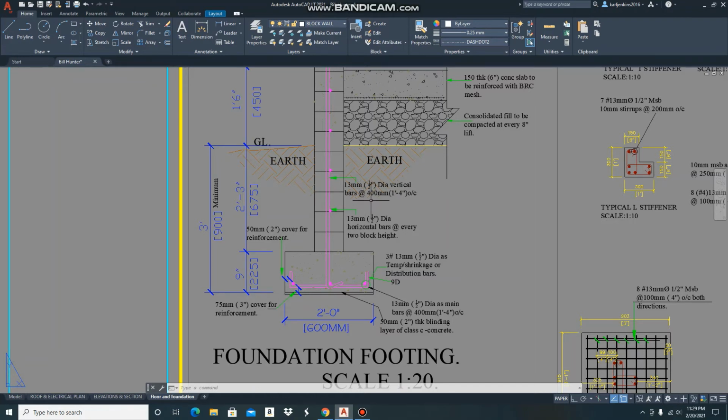You can check by multiplying your wall thickness times 3 to come up with the width of your foundation or your width of your footing. Your width of your footing is 3 times the thickness of your wall. That's your minimum width. It can be more, but not less.